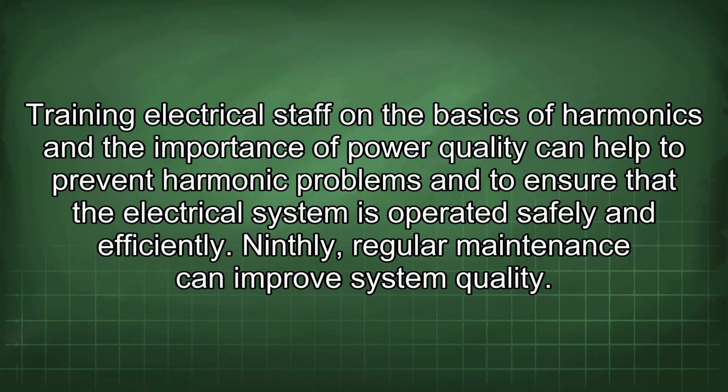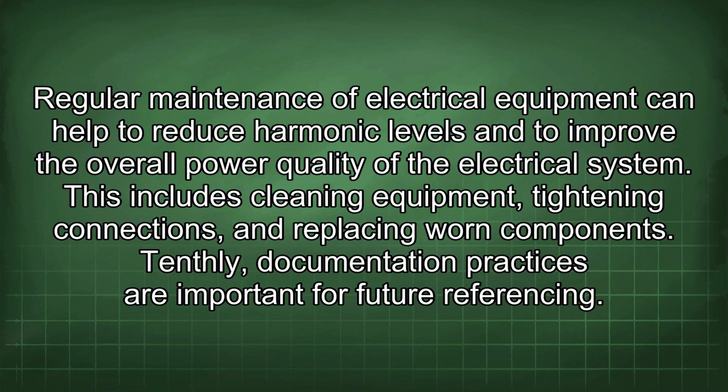Ninthly, regular maintenance can improve system quality. Regular maintenance of electrical equipment can help to reduce harmonic levels and to improve the overall power quality of the electrical system. This includes cleaning equipment, tightening connections, and replacing worn components.